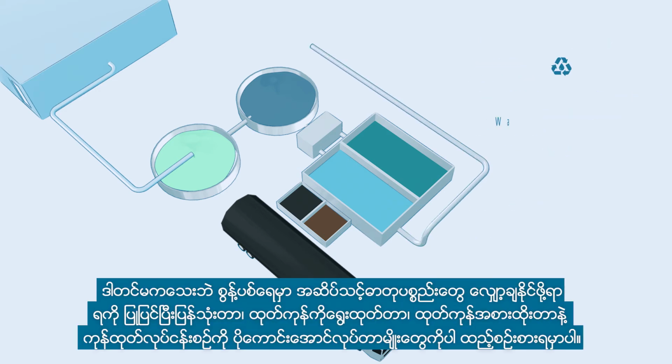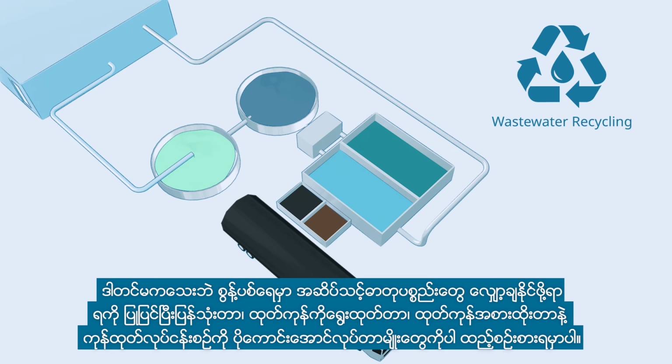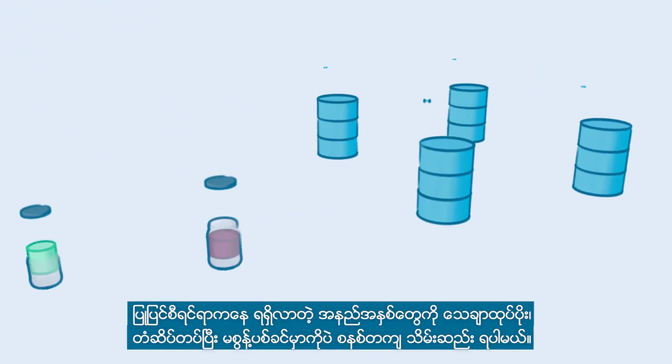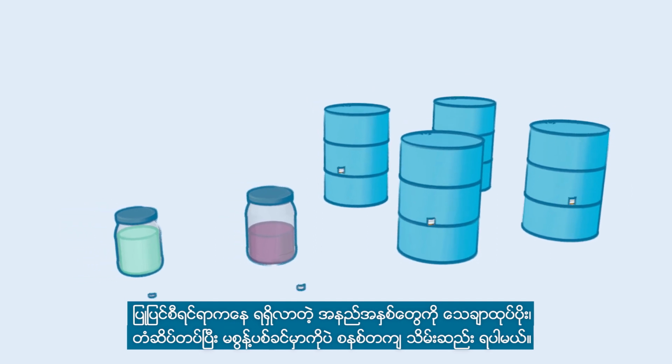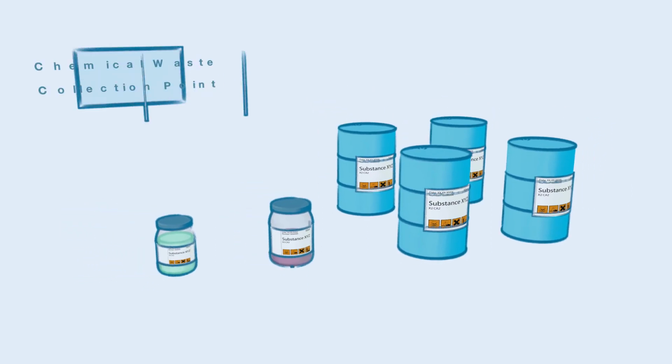Also identify and explore opportunities such as recycling and reuse of water, product selection, product substitution, and process modification in order to reduce pollutant and toxic chemical loading in discharges. All hazardous waste, including the treatment sludge, should be packed, labeled, and stored properly before collection.